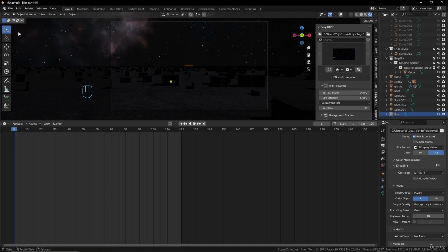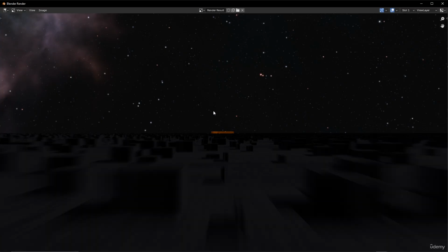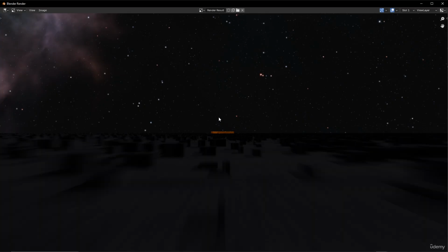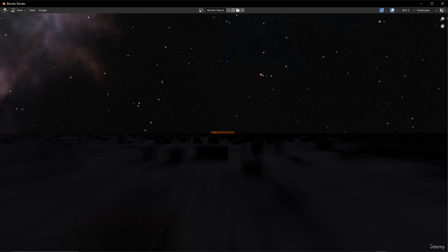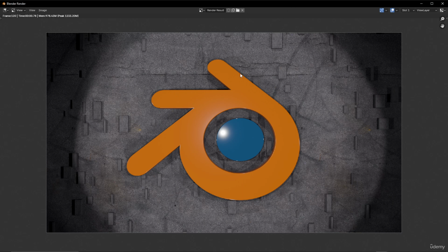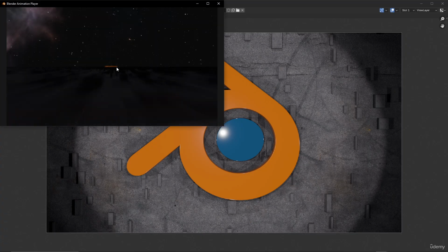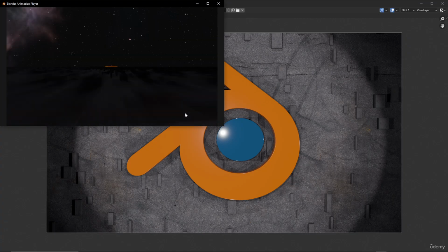When I want to render an animation, you can see that it's Control F12. So let's do that, Control F12. And now it will render all the frames of my animation, so it might take a little time. And when it's finished, I come back to you and show you the result. Okay, it's finished. It wasn't that long actually. And now if you want to play, you just use Control F11 to show the result here. So you can see the result over there. Okay, and you will have the animation just like that.